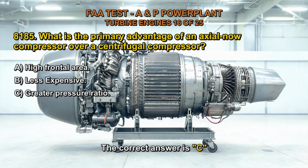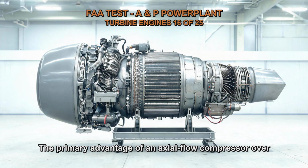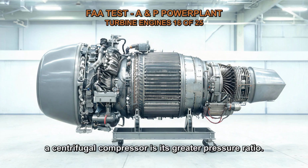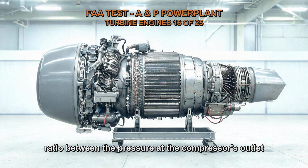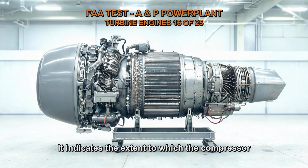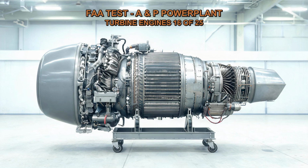The correct answer is C. The primary advantage of an axial-flow compressor over a centrifugal compressor is its greater pressure ratio. The pressure ratio of a compressor is the ratio between the pressure at the compressor's outlet and the pressure at its inlet. It indicates the extent to which the compressor can raise the pressure of the airflow.